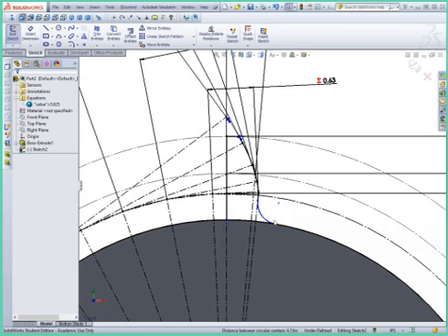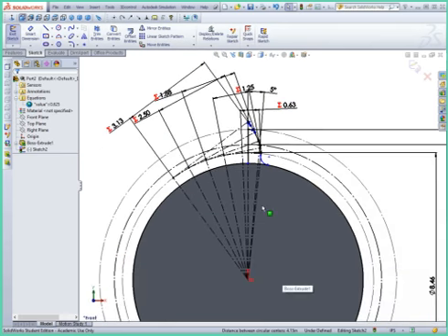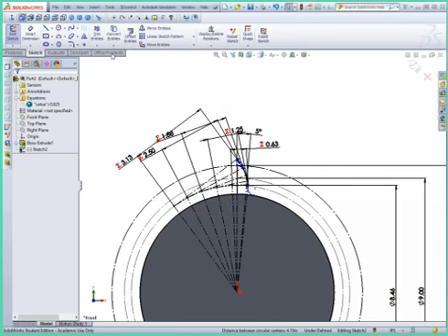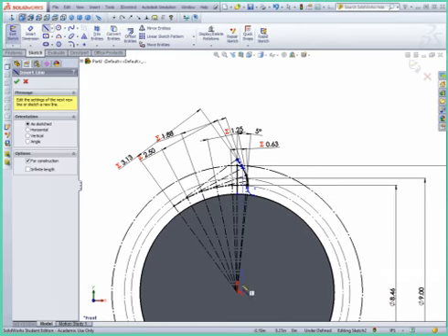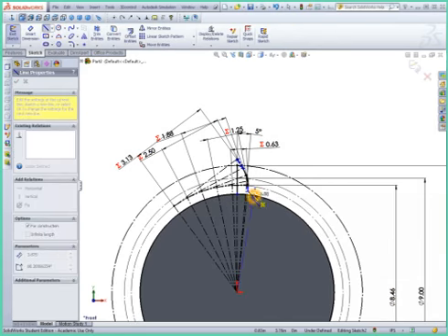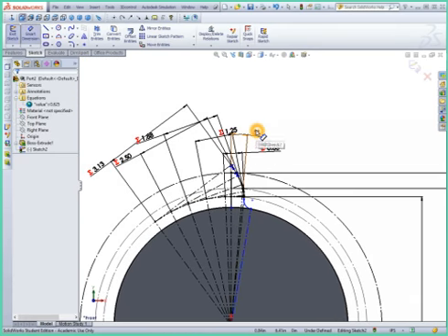And so this will actually be the midpoint between teeth, and I can define that exactly. I know exactly what the tooth width is. I calculated it before and used an angle to do it. And we could do the same thing again. So I can actually draw a center line from here to here, and I can specify that angle. And it's going to be twice as much as that previous angle.